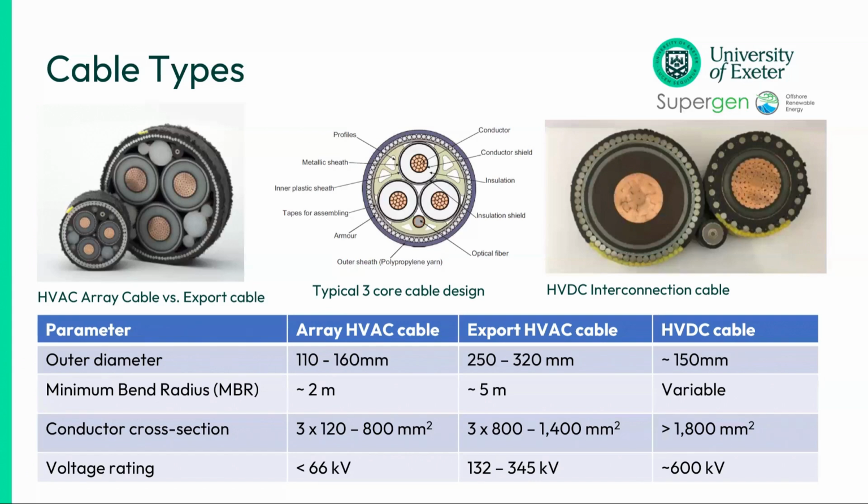Yeah. So again, almost competing design objectives. You could build a more dynamic cable at lower voltage levels, but then you're not meeting the voltage levels for the 15 plus megawatt turbines.